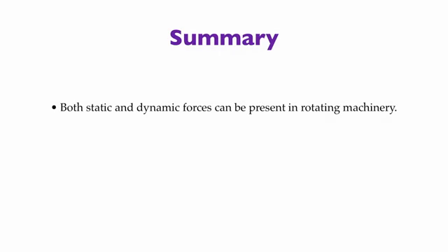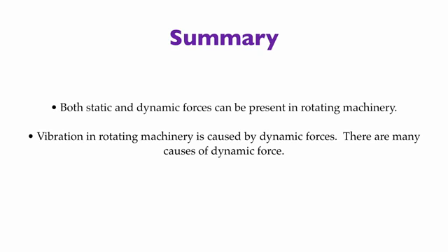Much of the mechanical deterioration and eventual damage to our rotating machinery can be attributed to the static and dynamic forces acting on our machines. Forces that are changing their direction or periodically increasing then decreasing are defined as dynamic forces. Dynamic forces are the source of the vibration that occurs in our machinery. Vibration analysis is a powerful diagnostic tool and can assist us in determining what might be causing the vibration to occur.